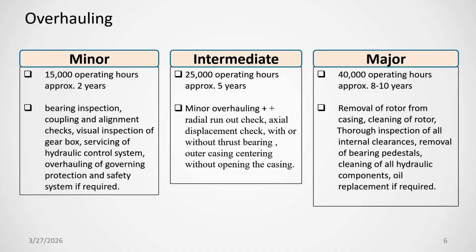We keep the rotor, do the centering, and then do the alignment, cleaning all the hydraulic components. Oil replacement is very important. During major overhauling, whatever the condition of your oil may be, you have to replace the complete oil. The capacity may be very high, but you have to replace the complete oil of the turbine lube oil system, and these are the jobs involved in major overhauling.